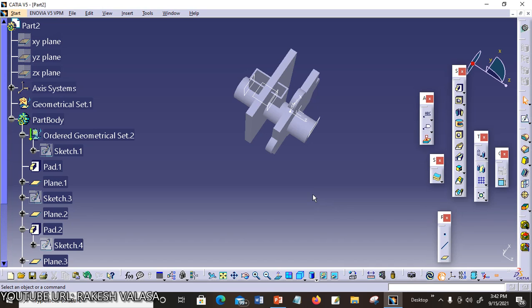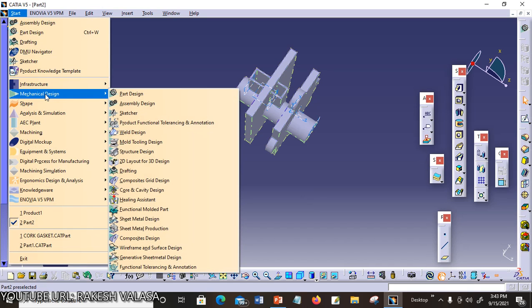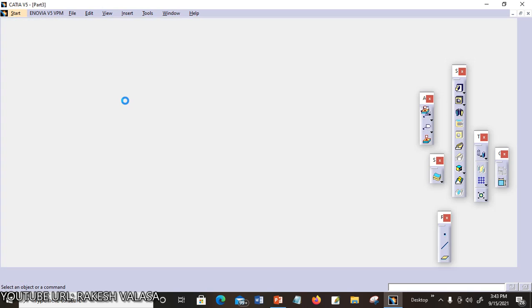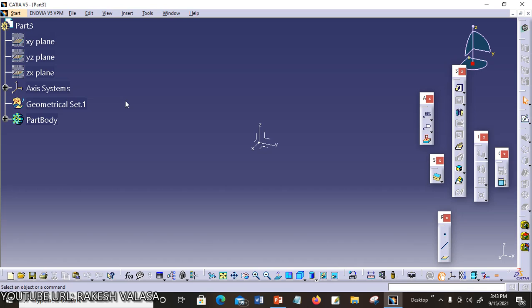In this video lecture, I am going to explain how to create pads in Catia V5 software. First open Catia V5 software and activate part design: start, mechanical design, part design. Now the part design is activated.